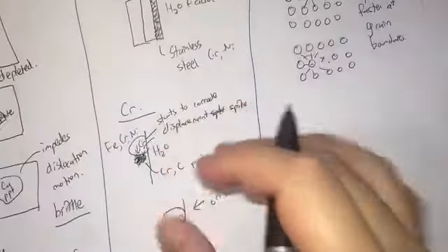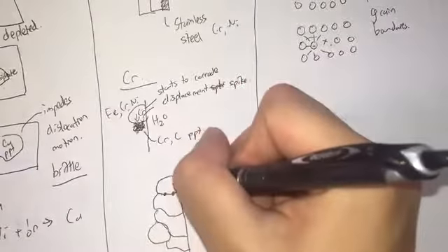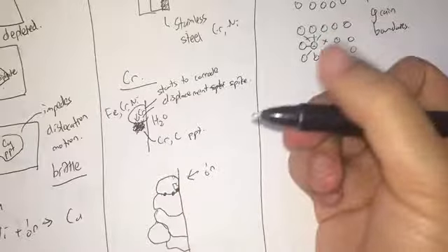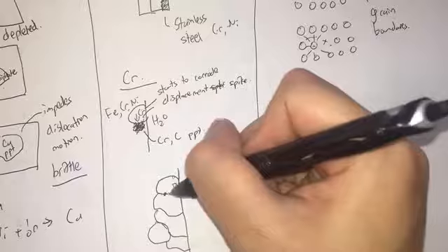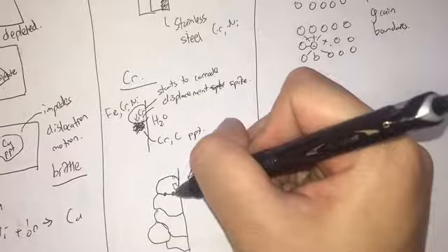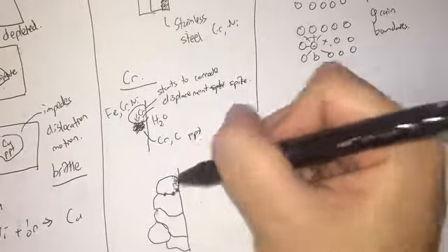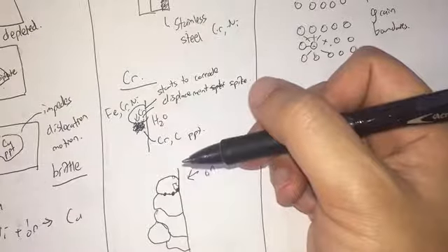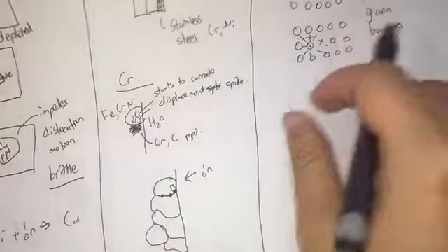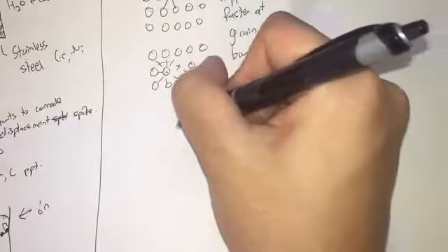So if we have a vacancy cascade here at the grain boundaries, what tends to happen is that the chromium at the grain boundaries is drawn into these clusters, and then at the grain boundary itself, the chromium content is severely depleted. So let's do a zoom in.